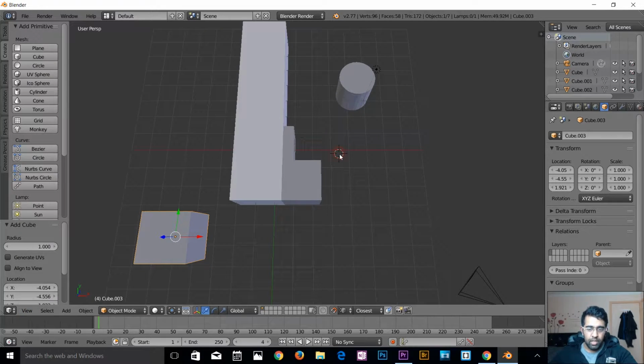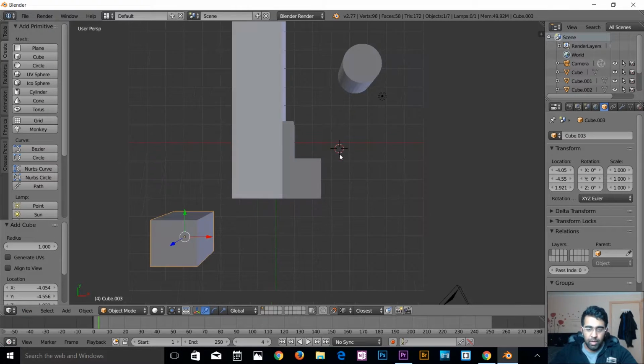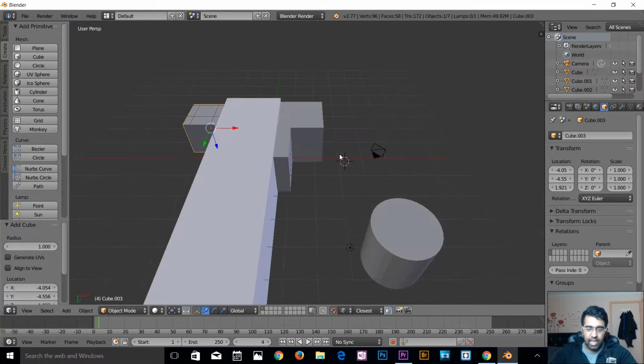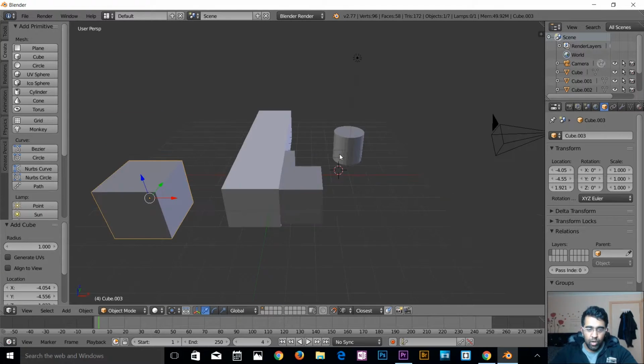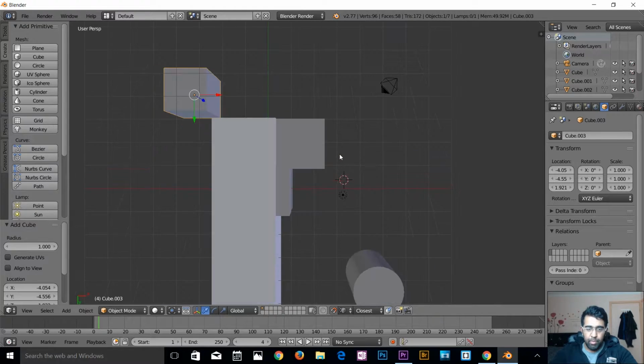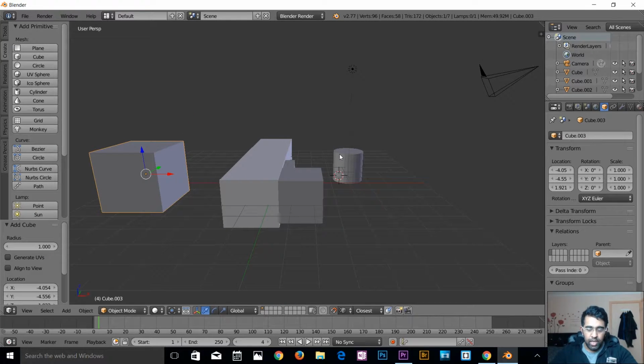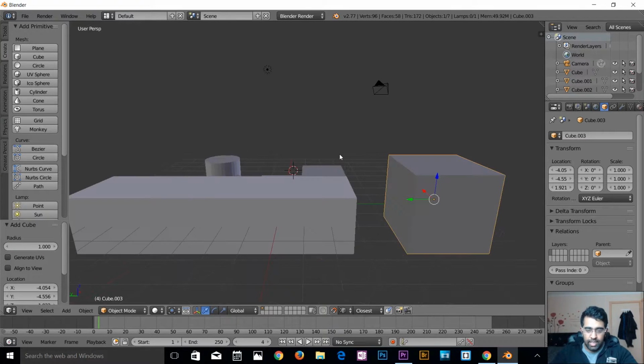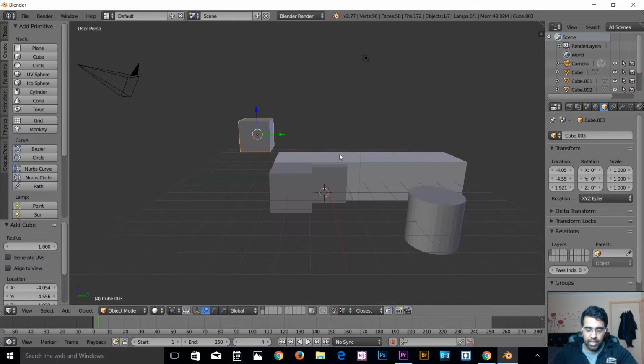Let's try them now. I'm going to orbit up, so I'm going to press num8. As you can see, it's orbiting on the x-axis. Let me go back and get the front view. If I want to orbit around the z-axis, I can press 4. That's orbiting, and you can keep pressing.